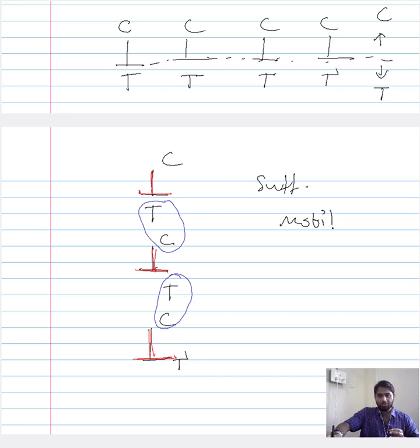This rearrangement requires sufficient mobility, and this is offered to us through the high temperature under which we are studying our material. So in addition to the annihilation, the system itself rearranges the dislocation in order to reduce the overall energy of the system.